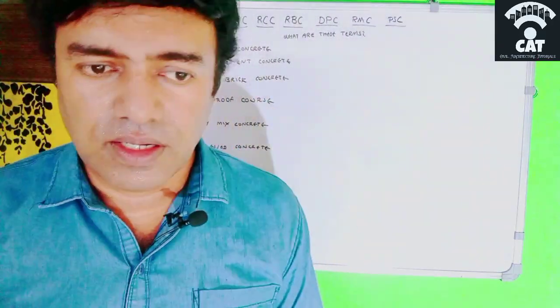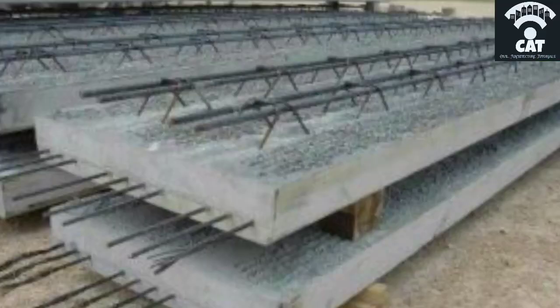PSC is pre-stressed concrete. I think I did one video exclusively on pre-stressed concrete, in which you know that the structural member, that is the steel, will be pre-stressed. The tension will be added to the steel prior to the concrete. According to the design load, they will analyze the load that will be coming into the structure, and based on that, the level of tension we can give to the steel, we can give prior to the concreting.